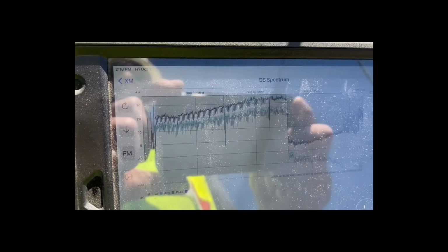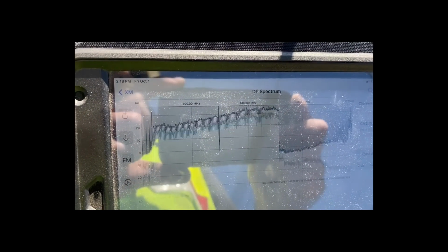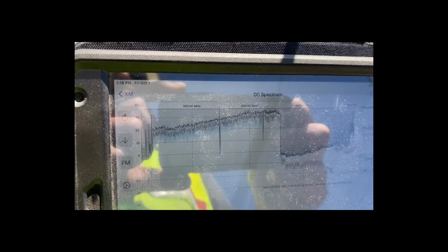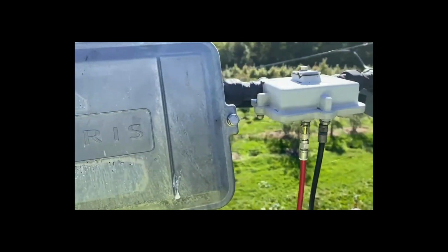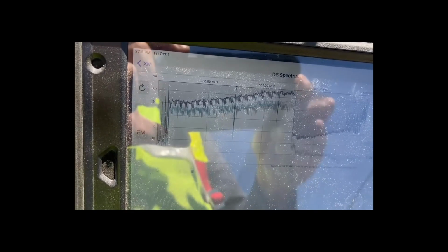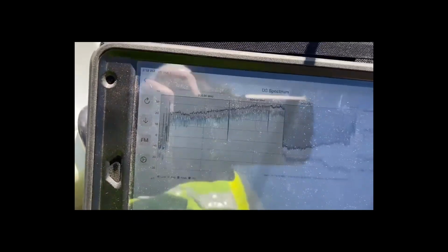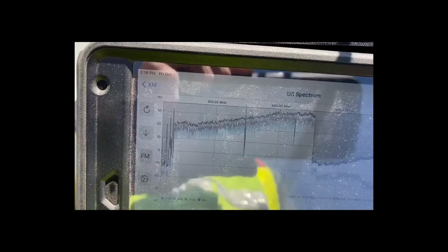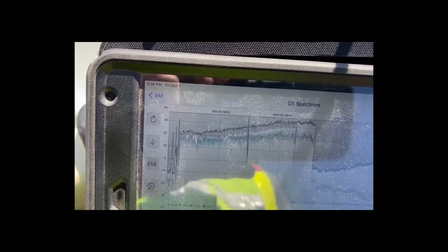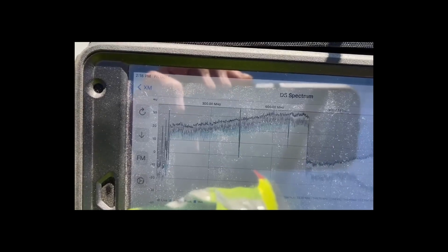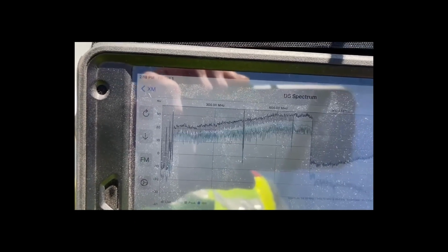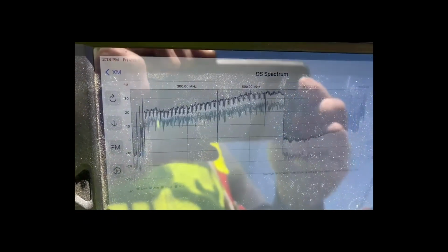Okay, the mystery makes sense now. So in the full band capture responses of all the devices that are past this line extender, this is a 1 gig Aris 331 line extender, we had this really weird periodic, kind of quasi square wave on the downstream, and it didn't really make sense. But now that I'm up here and connected to this amplifier, I think during the period of time that we were capturing those traces, you can see that the output response of this amplifier is just bouncing across the entirety of this spectrum. So now that quasi square wave actually makes sense.